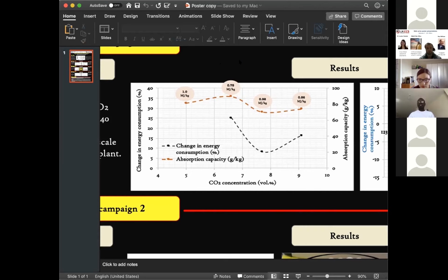Selective exhaust gas recirculation in series is basically a process where CO2 in the treated gas downstream of the CO2 capture process is being captured and recycled back to the gas turbine in order to boost the CO2 concentration in the exhaust gas.